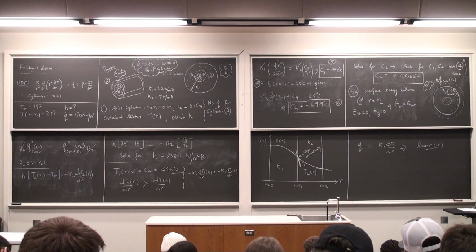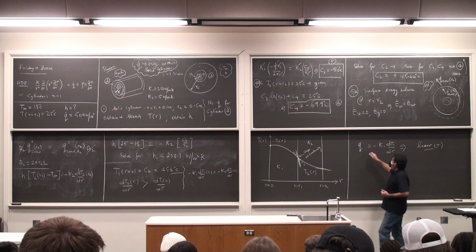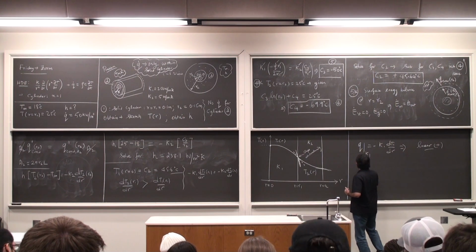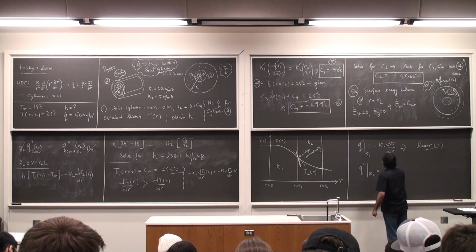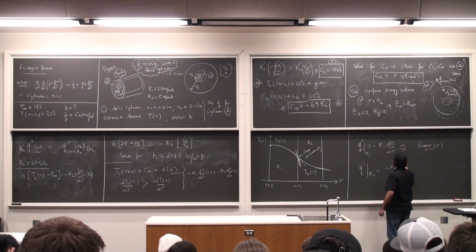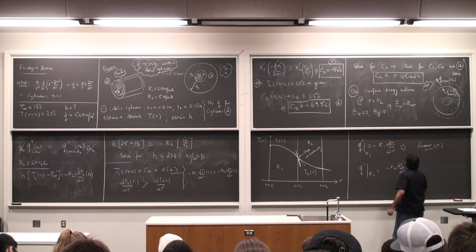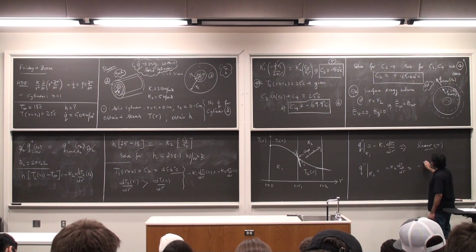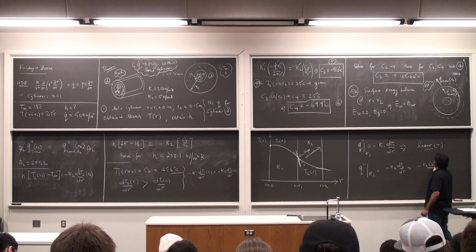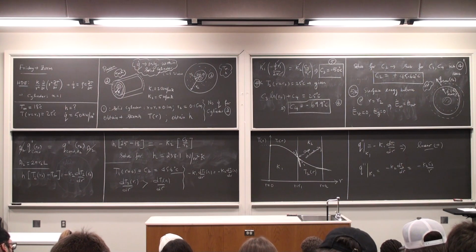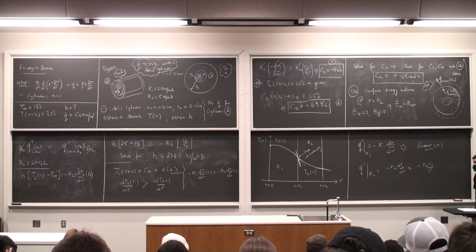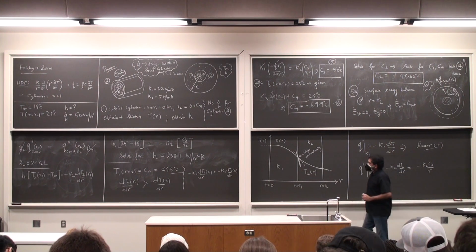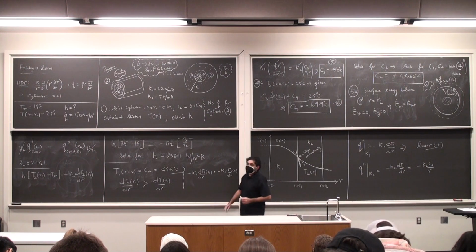And then if you look at the second one, at material K2 it is minus K2 dT2 by dr, so that's going to be minus K2 C3 by r. So this is a 1 by r dependence, so non-linear here, but negative. Alright. Any other questions on this problem, please?